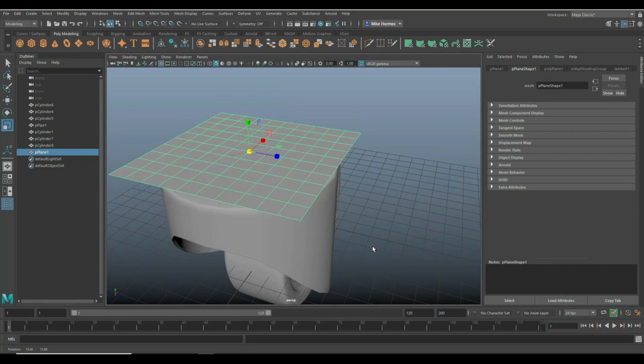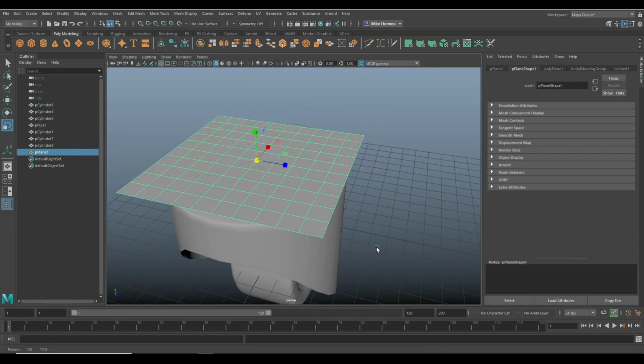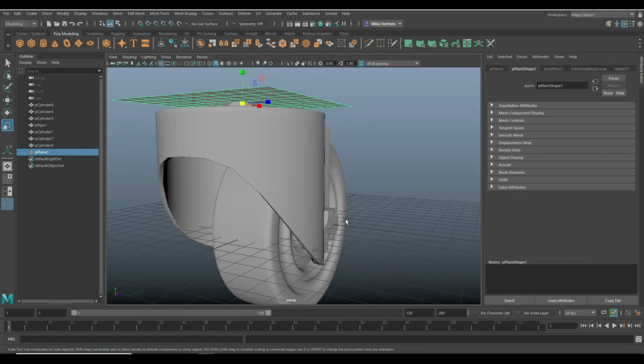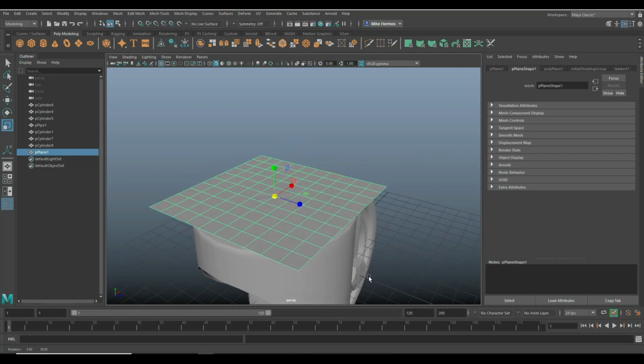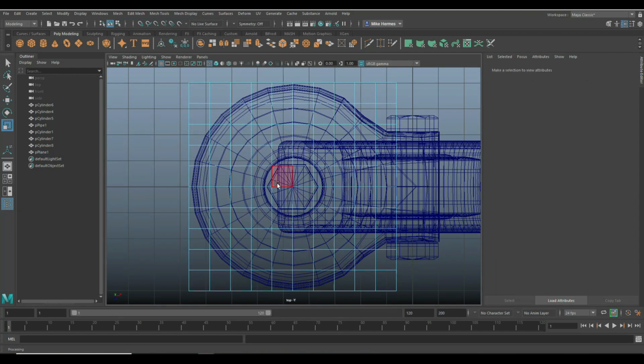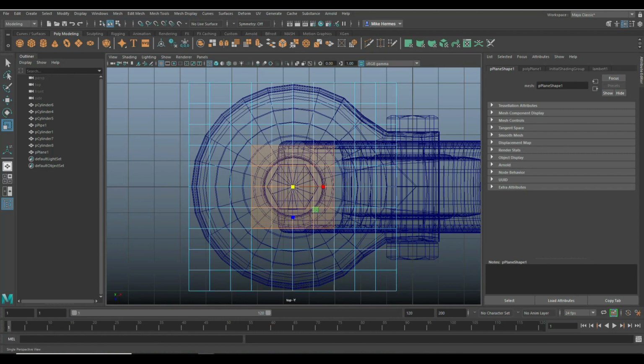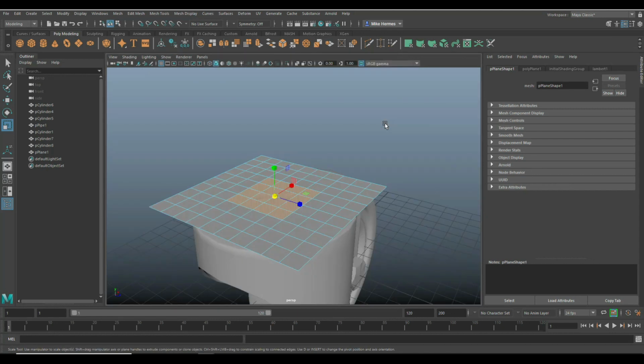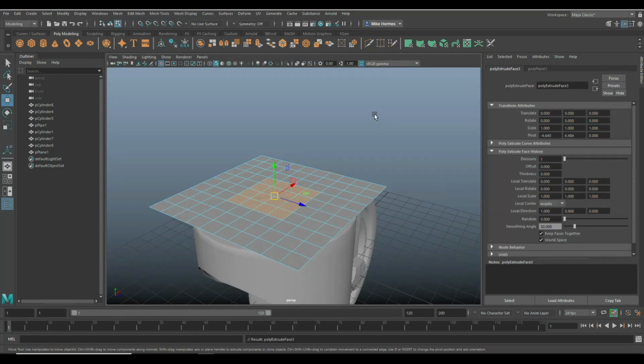Okay, and then what you want is to shape it. Well, you don't have to, but what I would do is I would bring it up a little bit. I'll show you what I mean by that. So you need to have clearance for that head, right? So we're going to go to Face, hold down the Tab key, and at the very least you want to have this area right there. Okay, so what you're going to do is you're going to hit Control E, you're going to hit W, and you're going to pull that down something like this.